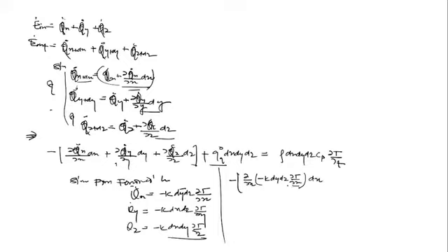And these all terms are inside the differentiation. Similarly, plus del upon del y of minus k into dx dz into del T upon del y, bracket close into dy, plus del upon del z of minus k into dx dy into del T upon del z into dz.